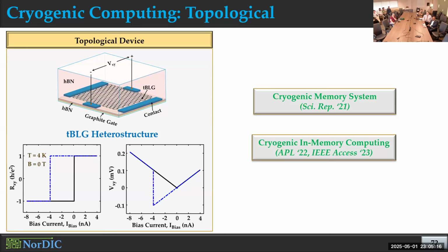And for logic circuits, one of the major challenges that we observe is the switching voltage of the ferroelectric material. The ferroelectric material that we used, lead zirconium titanate, had a coercive voltage of plus minus 4 volt. That's a large voltage, and that was one of the limiting factors for the logic circuit, because if we have plus minus 6 volt at the input, we also need plus minus 6 volt at the output. And to generate that, we had to spend large power. But if we have a ferroelectric material that can switch with 1 or less than 1 volt, then that will be a significant improvement in power consumption and energy efficiency of the whole logic circuit.